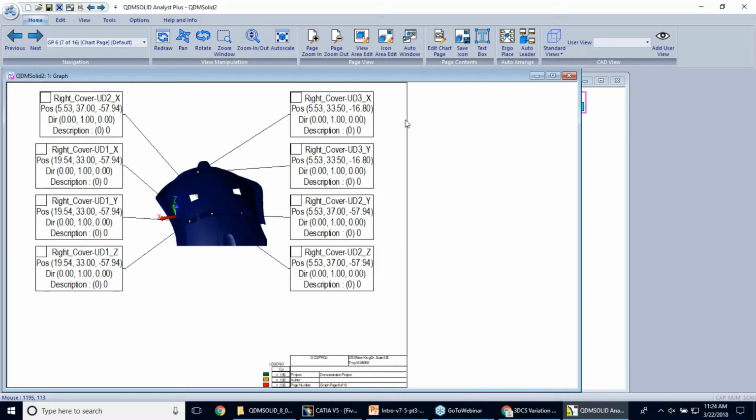Yes, we do have a few different tools in the software where if the points are all based off 0, 0, 0 and the CAD is out in assembly coordinates, we do have a few tools that will line up the points onto the CAD. It's almost like a 3DCS move where you pick the point, you identify the XYZ location, such as you could take a point and choose the center of a hole, say, all right, that's point 1.